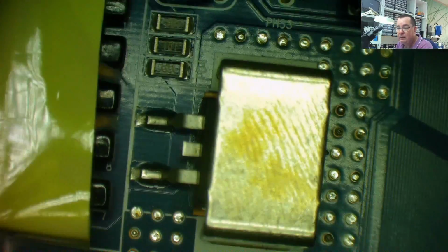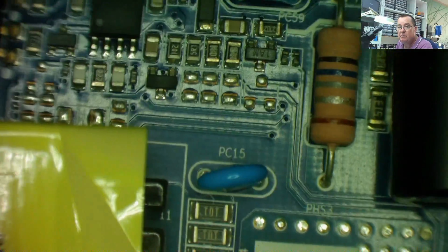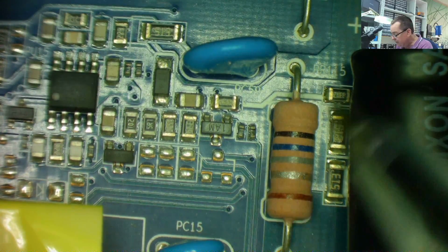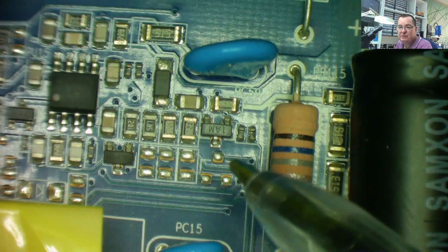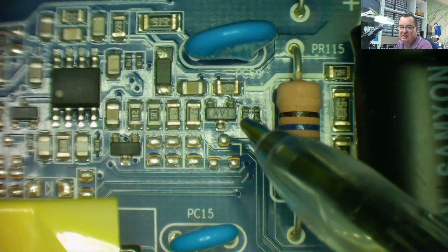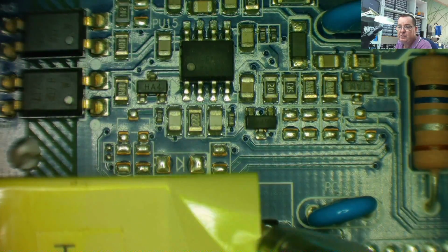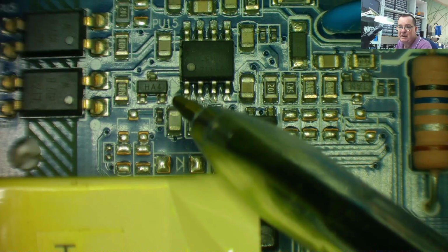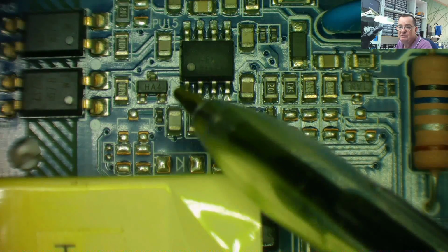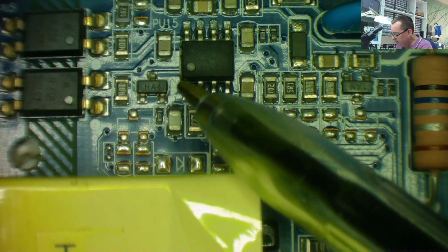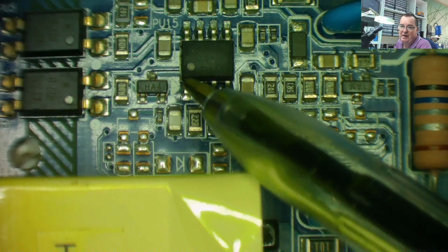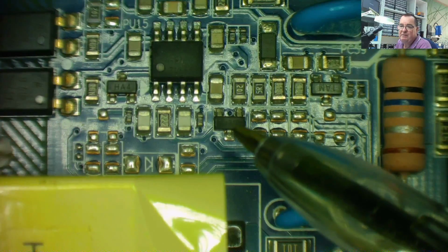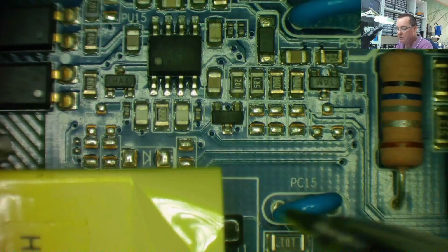Often you'll find diodes that look like these sort of devices. Now these can be transistors or diodes. This one, 1AM, actually is a transistor, I know that. But you can find diodes in this type of package as well, which is called SOT23. Small outline transistor 23, which is 2mm by 3mm. In actual fact, these can be diodes or even dual diodes in the same package. So you'll find diodes in that type of package as well.